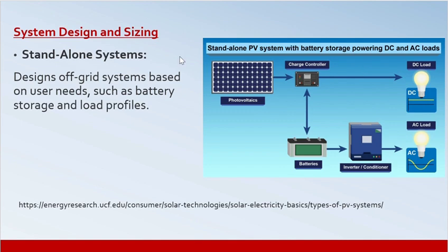You can see in this picture, PV panels convert sunlight into electricity through the photovoltaic effect. When sunlight hits the semiconductor material in the PV cells, it knocks electrons loose, creating an electric current. PV panels generate DC electricity, as you can see, but it can be converted to AC electricity using inverters.